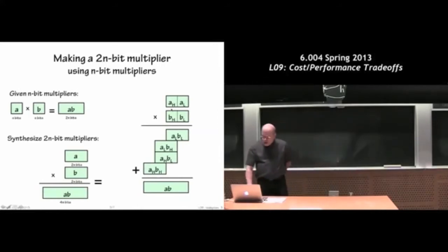And this is a diagram that shows us how to break the 2n times 2n multiplication into a series of, sort of, block by block multiplications. If you thought of each of these as, if you will, a digit, the thing that we know how to implement, in our case it's the multiplication table, but in this case it's n-bit multiplication. You can see we can parlay that skill of being able to do an n by n multiply by breaking this big problem down into 4 subproblems, which will create these 4 partial products.